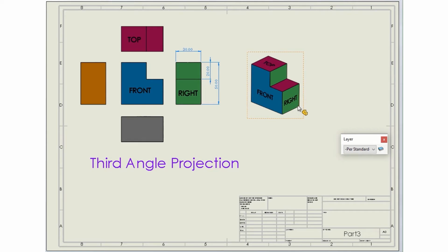In this short video, I'm going to show you about layers on a drawing. So we're in SolidWorks here, and all I've got you to view is the drawing page itself. You should already be familiar with the fact that we have two layers. This title block and outer border that we have behind our drawing is greyed out and is not editable, and I can't do anything with it. However, all the information that sits on top is on its own layer, and I can move this about and change things and add bits and pieces to it.